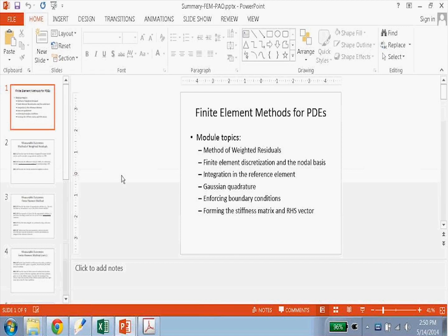So, for example, if we look at the linear nodal basis in 1D, remember that these hat functions have the property that they are 0 at all nodes except their own node where they're equal to 1. So this is a plot of Bi. It's got a value of 1 at node xi. It goes to 0 at node xi plus 1, and then it stays 0 for all nodes to the right of xi plus 1. It also goes to 0 at xi minus 1 and stays 0. So the basis function is actually defined on the whole domain at 0, and then it's up to 1, down to 0, and then stays at 0 for the rest.